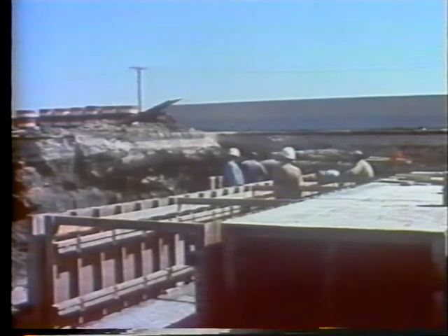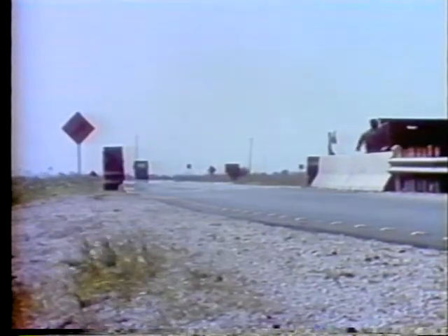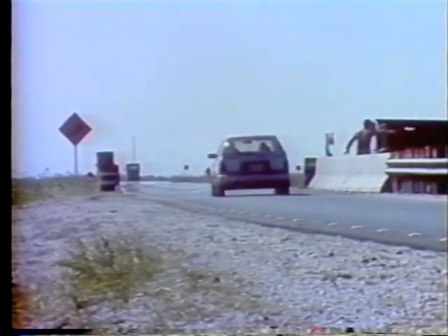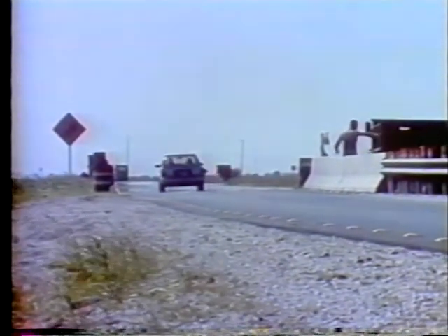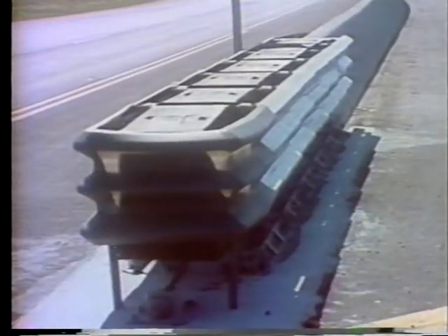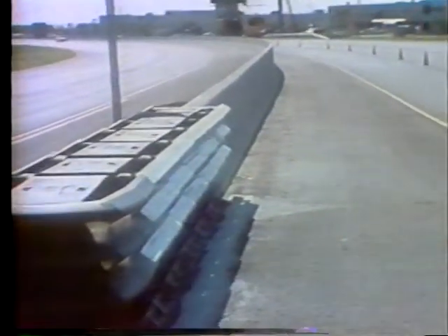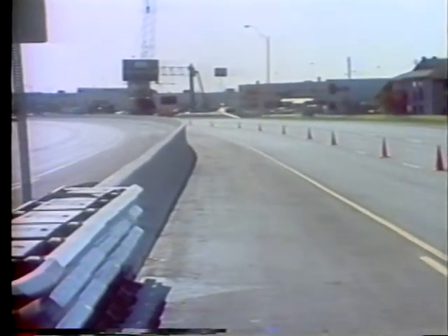With a concrete barrier, maintain a 2-foot buffer between the barrier and the traveled way. Proper treatment of the barrier end, such as a crash cushion, is required. The barrier should be properly delineated.